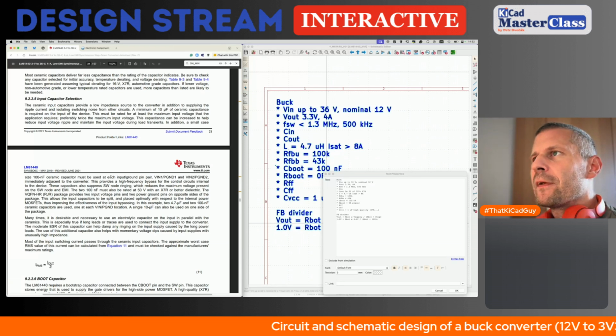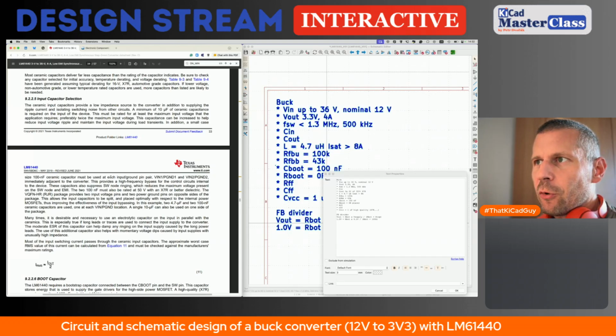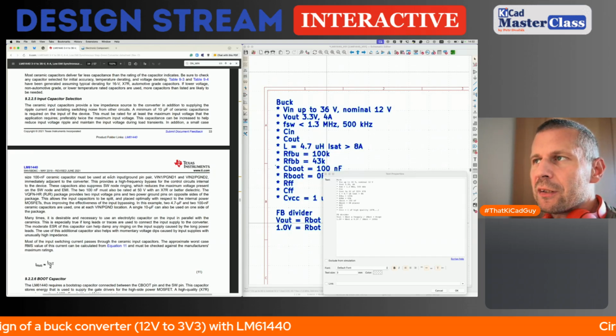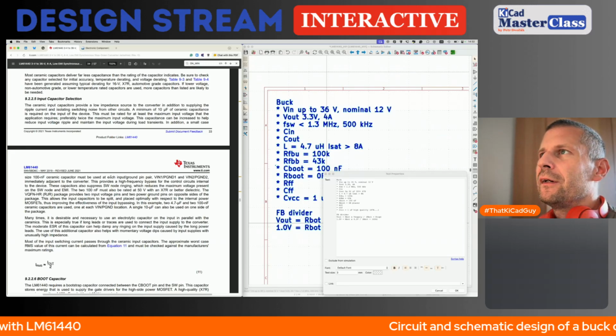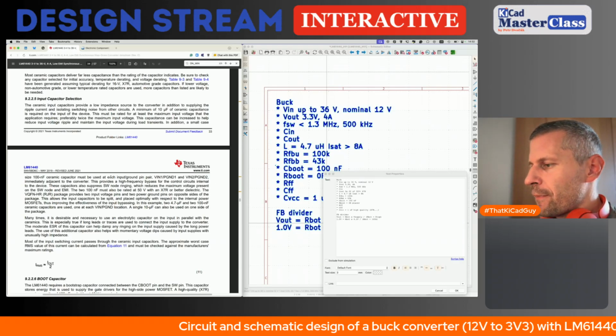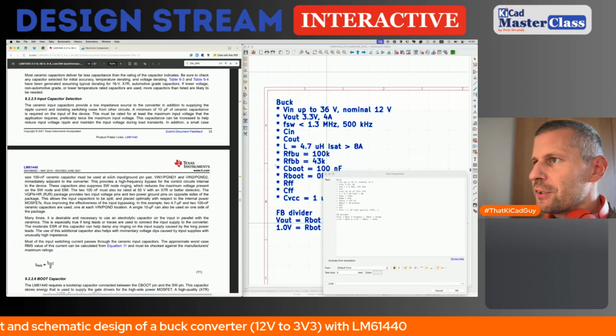When we want 4 amps at the output, there is some efficiency of the converter, but the voltage is 4 times higher at the input than at the output. So the input current will be, let's say, 1/3 of the output. So when we have 4 amps at the output, 1/3 is 1.33.